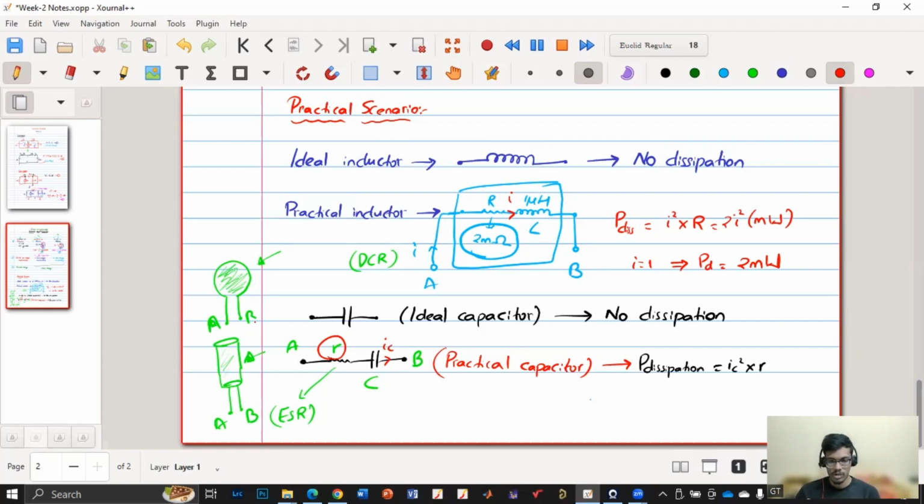So overall, when you are talking about an inductor, there is some resistance sitting inside that inductor, like in series, when we talk in an equivalent sense. So they are not trying to make that resistance. They are trying to only make the inductor, but whatever wire they are using, etc., will have some finite resistance, and that will appear as if it is in series with the inductor. So because of that, we'll observe a few parasitics in series.